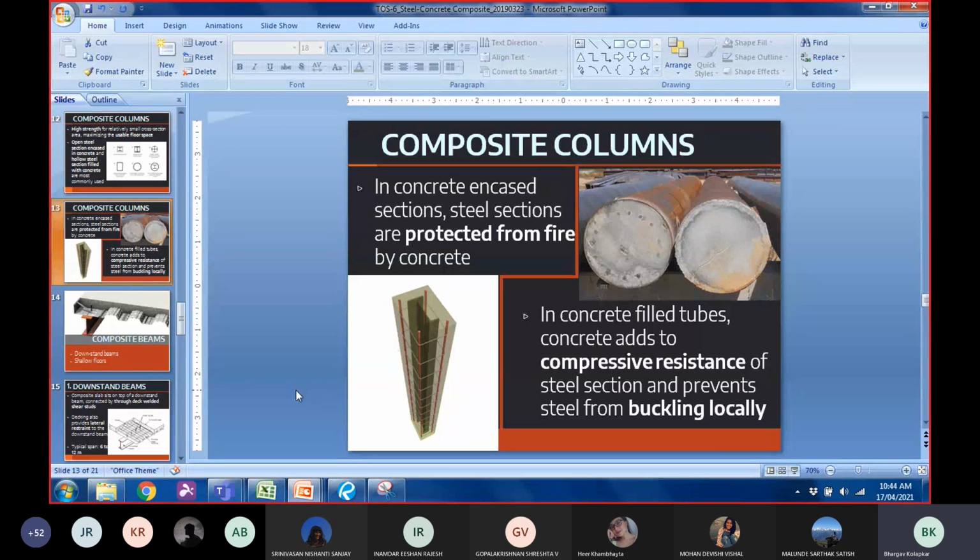You always try to strike a balance between the cost of the space and the cost of the construction. So the client went ahead with the reinforced concrete even though the sections were larger. So it depends on a number of factors, and an extensive study has to be undertaken to understand which system is really most efficient in terms of cost.